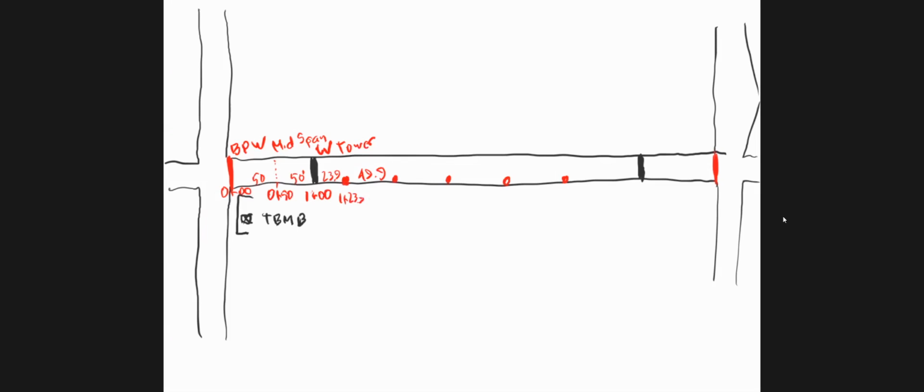And then 49.9 feet later, you'd have station 1 plus 73.8. Remember, stations are cumulative as you go all the way across, okay? And each light is 49.9 feet apart. Then you've got the tower down here. For some reason, this last distance is 50.2 instead of 49.9 that the rest of them are, okay? And then this distance 50 and this distance is 50, okay?